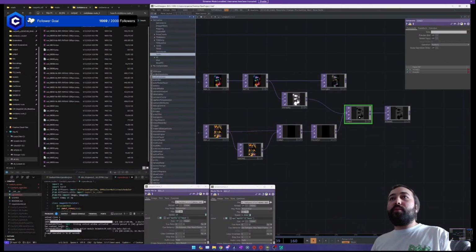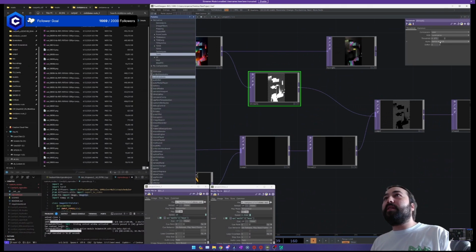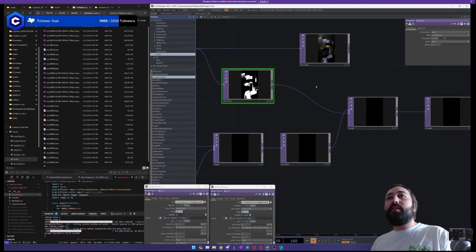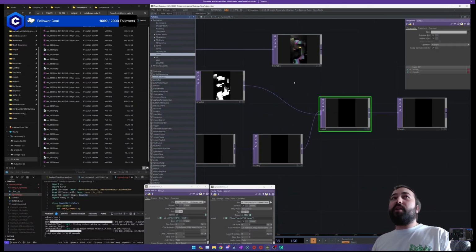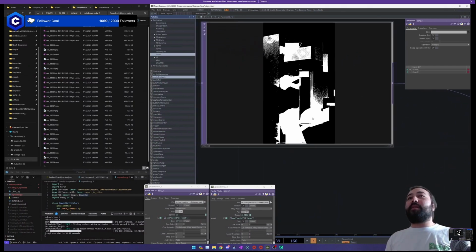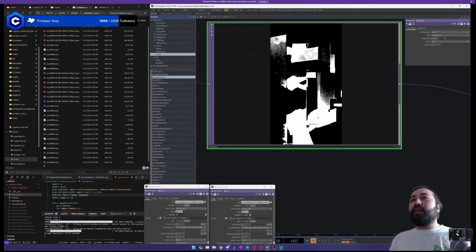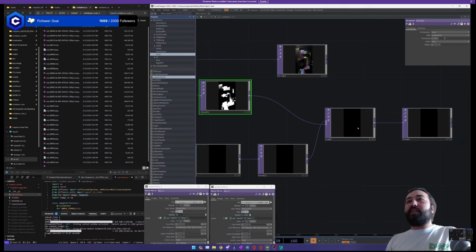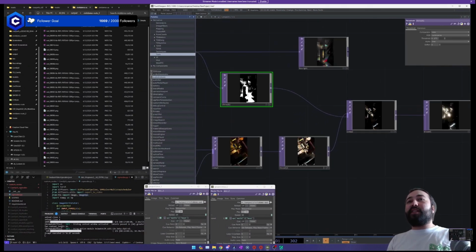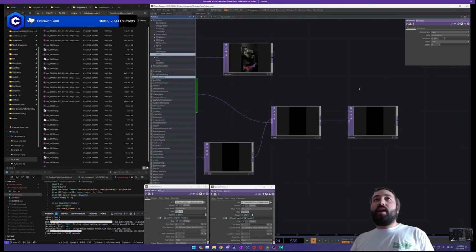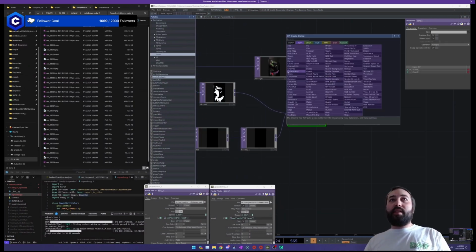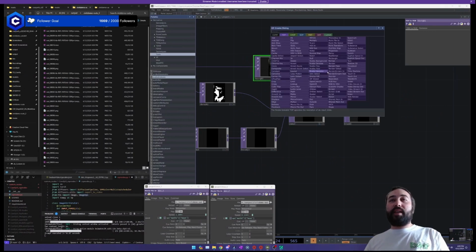And we're going to do it like this, and we're going to use a multiply. Oh, you know what? Let me change the alpha to be 1 because we don't want alpha. So I'm going to use multiply, and since we're giving it something that's black and white, everything white is going to be multiplied by 1, and therefore it'll go through, and everything black is going to be 0, so everything multiplied by 0 just becomes 0. So it's essentially going to mask it so that we're only going to see this snare thing within the boundaries of this threshold now.